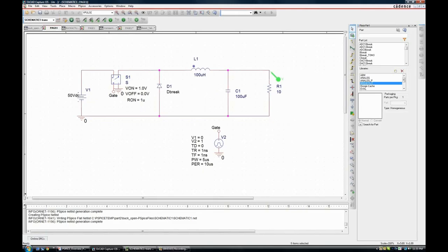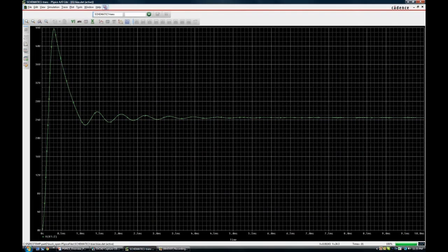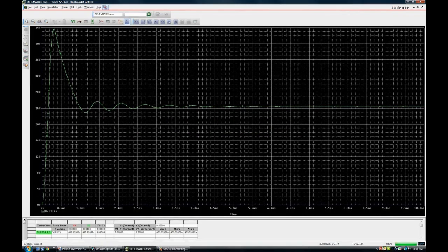And of course, as soon as we mark it, it turns green because it's a live simulation, and here's our data. And again, that terrible overshoot because we're running that buck converter open loop. So if I want to look at cursors, of course I can toggle my cursors here and I see the values. I can get the maximums, the cursor peak, the local min, local max, the slope, and these sorts of things by these buttons across the top here.